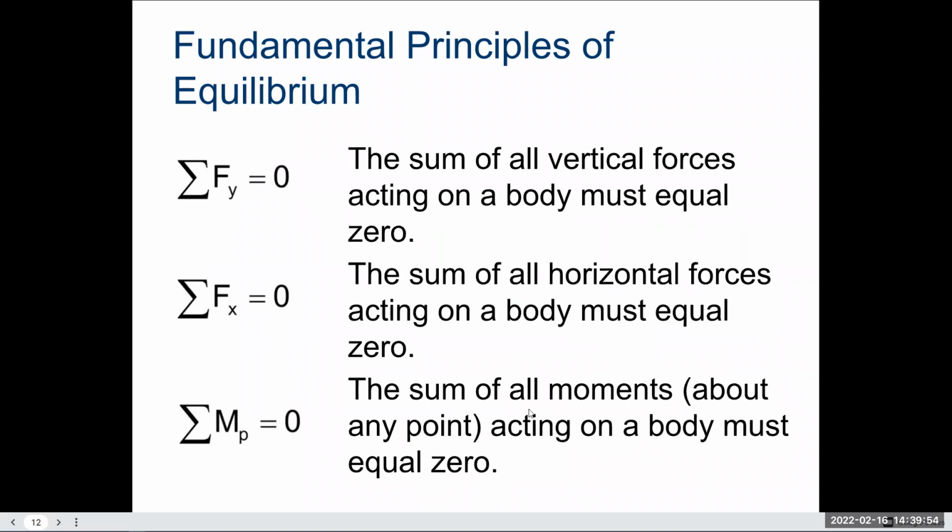All right, so the fundamental principle of equilibrium is, again, we want all of our forces and all of our moments to sum to 0. So here we have our sum of forces. The sum of all vertical forces should come out to 0. The sum of all your x forces should go to 0, and the sum of all your moments should equal 0. We want that to happen because if it's not, that means there's going to be unbalanced force, and that oftentimes is where we'll start seeing structural failures.